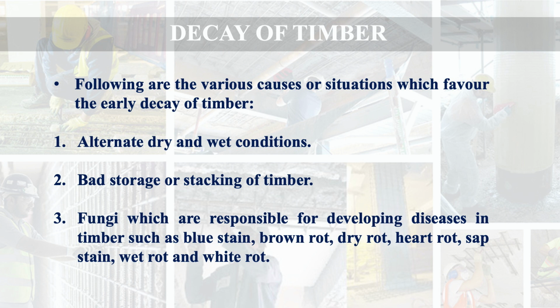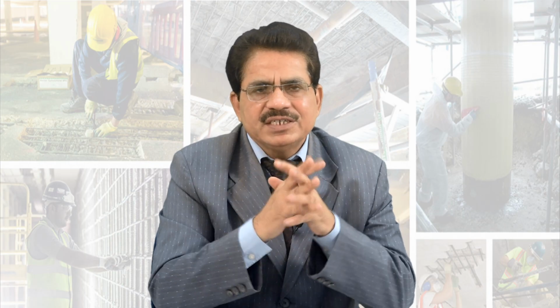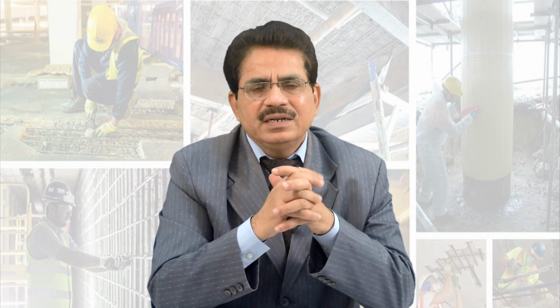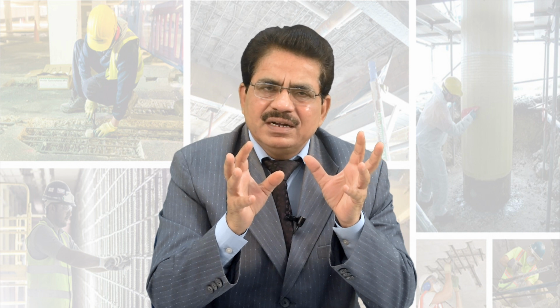Then fungi which are responsible for developing diseases in timber, such as blue stain, brown rot, dry rot, heart rot, sap stain, wet rot, white rot, etc. Then improper seasoning means if the seasoning is not done properly, then certainly this unseasoned timber will be liable to attack by many fungi, insects and the natural forces also, and it will decay quickly.